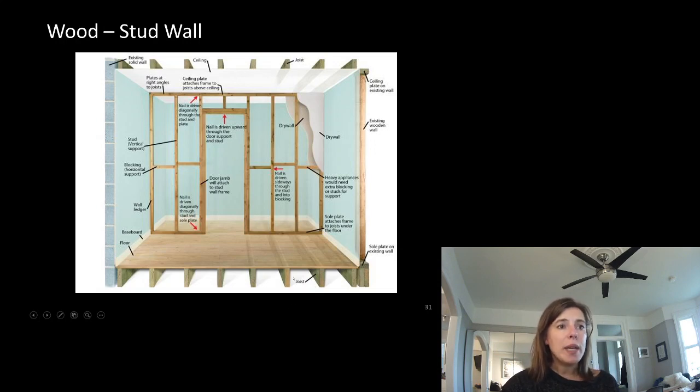You can see joists down here that look like they're at about 16 inches on center, and a ceiling joist up here, which are about 16 inches on center. And look at this. They've tried to line them up with roughly where the studs are, too. You don't have to, but it's good practice.